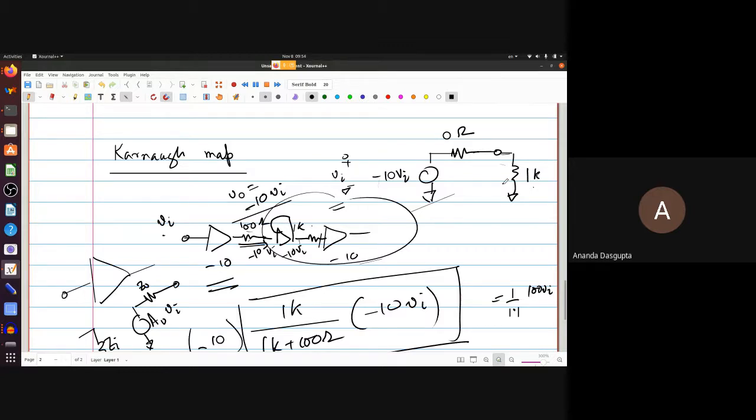So if you're given the input impedance and the output impedance of amplifier stages and asked what happens when you connect them together, you have to be careful. You have to be careful in the sense that whatever gain you would have nominally got from the first stage, that entire output voltage does not necessarily become the input to the second stage because of this potential division.